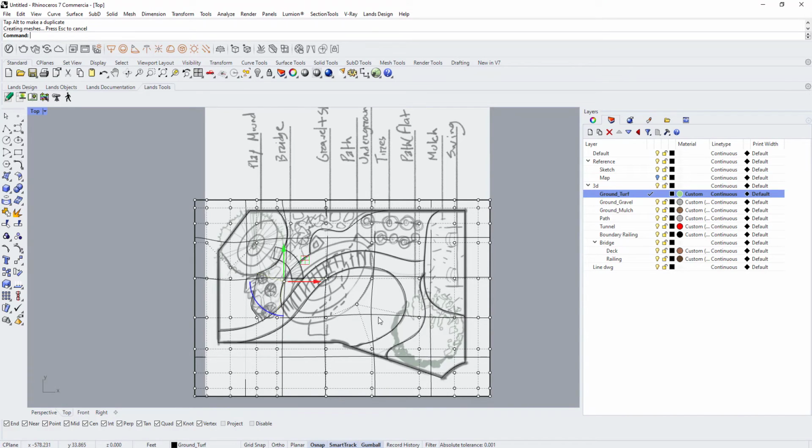They are in a way the most difficult part to understand, but also in another way quite easy. In order to start with the paths, all I have to do is trim out the ground plane where there is no path, and then create a certain thickness so that the path follows the ground plane, as we have done the grade change already.